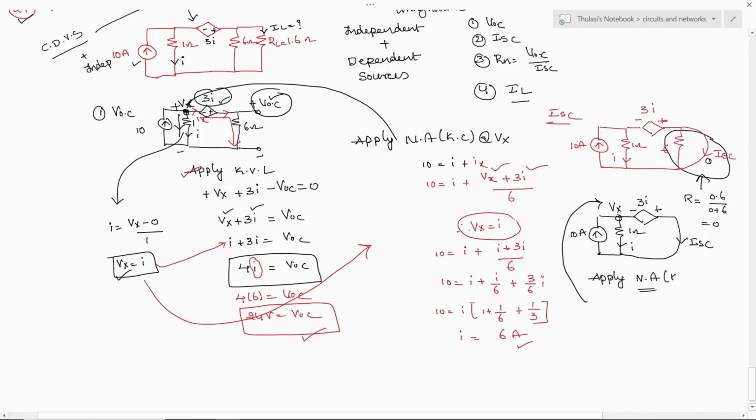So see here, this is the Vx node and this is the current. This is one voltage source and this is another voltage source, and this is the positive terminal and this is the negative terminal. So two voltages have to be linked to establish the connection. Current is flowing like this. So at the same point, linking these two, apply KVL. Current is leaving, so the leaving polarity of the voltage is plus Vx, and the leaving polarity plus 3I is equal to 0.